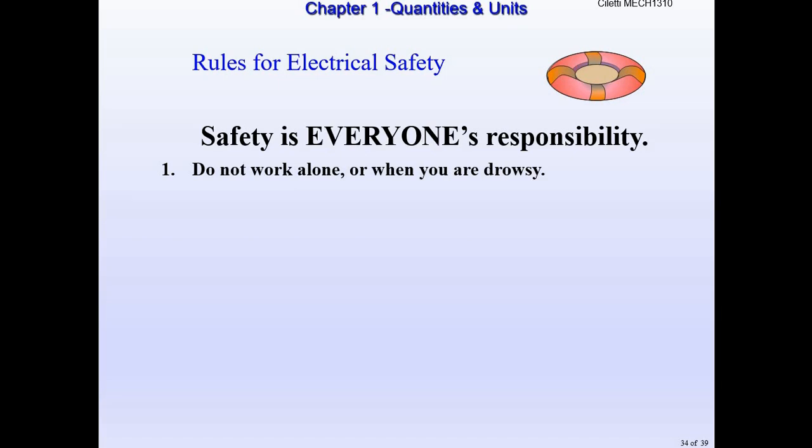If something does happen, especially with electricity, when you get shocked, it makes you clench your muscles, and sometimes you can't let go. You need someone to kill the power. But whenever you're working with electricity, you should always shut the power off anyways, okay? Don't wear anything that conducts. Don't wear your ring or tape it. Don't wear an electric watch.